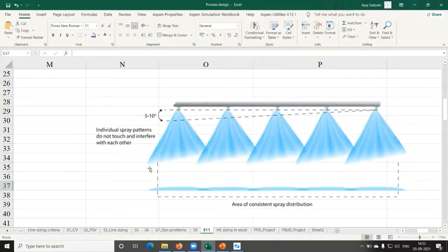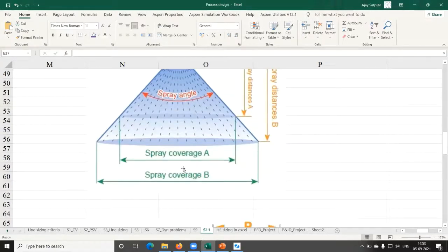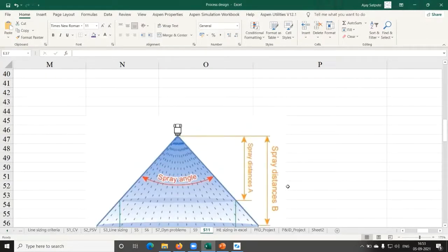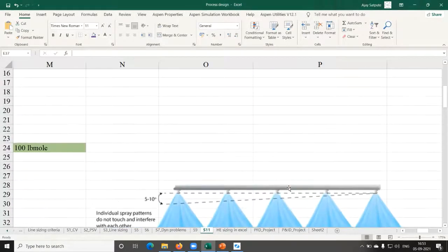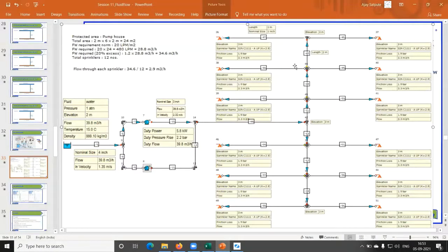The vendor will tell that if you give a minimum of, say, 1.5 bar gauge pressure at the inlet, then I can assure that the spray coverage area would be, let's say, 3 meters or 4 meters, whatever. Taking that information from the vendor, piping will create a diagram, the top view, and it is our job to approve that. Once that gets approved, then we'll prepare our model.